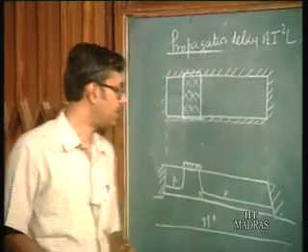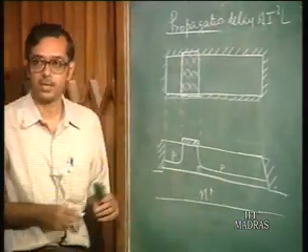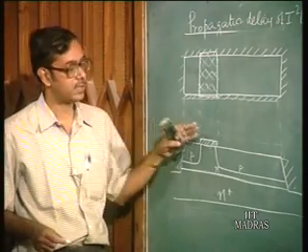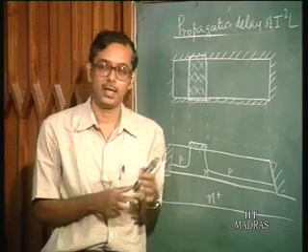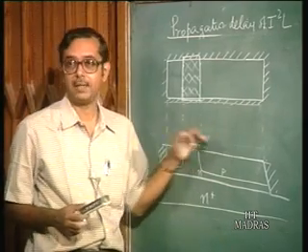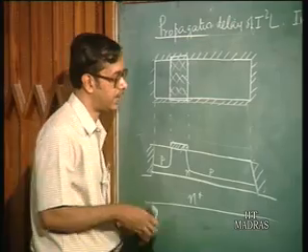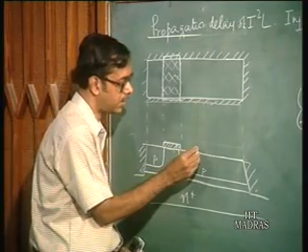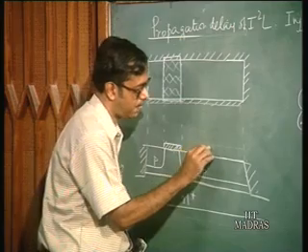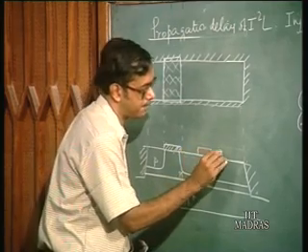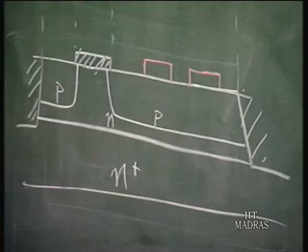So what is done is polysilicon is deposited, actually doped with arsenic, which is an N-type impurity. Polysilicon is deposited and again patterned, and you have a pattern like this. I shall draw it here. Maybe these are the polysilicon regions.